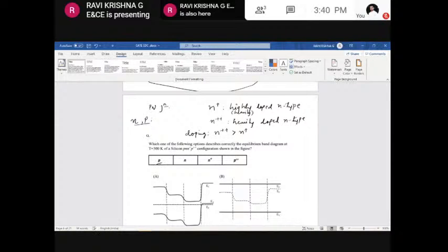This is moderately doped semiconductor material, whereas this is your heavily doped N-type semiconducting material, and of course the doping level of this N plus is greater than this N. And if you consider the extreme material, it is represented as P plus plus, which means this is again heavily doped compared to this P. So N plus is heavily doped compared with the N region, and P double plus is heavily doped compared with the P-type semiconductor region.